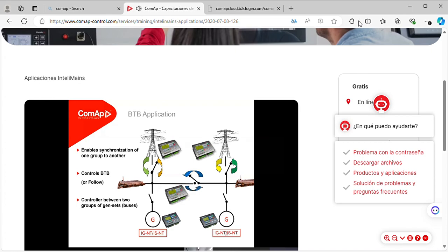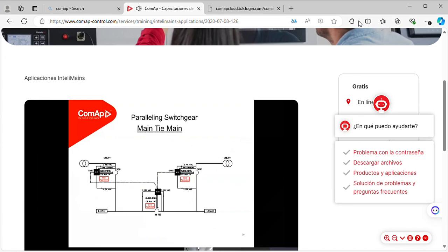Now looking into the third application, which is another interesting requirement, where we have basically a common bus or common coupler. So you have powerhouse one with, say, one or two or more gensets on two groups. There are multiple utilities, and in between I might consider having a bus coupler if and when required. Say for example, I can have dual bus, dual utility, and then I can have individual genset banks at both ends.